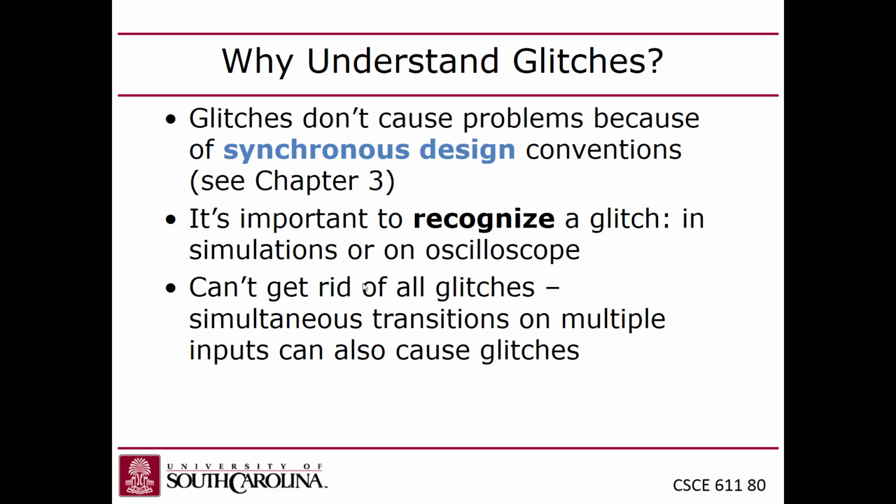Which makes glitches very common. But the output of the circuit is going to get captured into another register. And we're going to guarantee that that's not going to happen until the glitches are gone, the glitches have propagated out and stabilized. So usually you don't care about glitches. It's usually not a problem in practice.